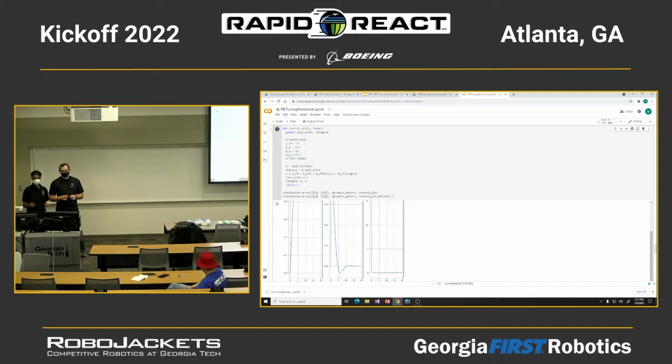So always consider before you start doing your control, is there going to be steady state error? If there is, then you would need I. If you don't see any reasonable reason for steady state error, then you only care about the P and D terms.